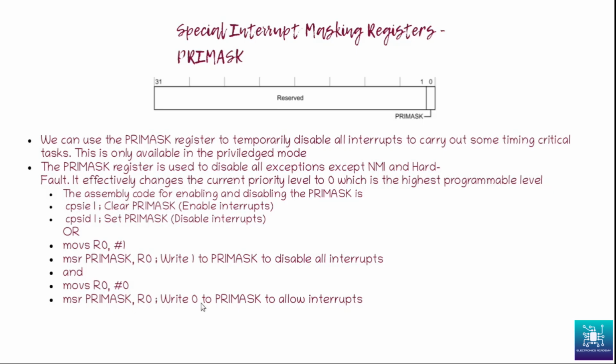We will see it more in our code, and as we discussed, these registers are not memory addressable, so they will have to be addressed through assembly code. So we'll have to have some inline assembly in our C code. We had discussed previously, and I said that you can absolutely do without assembly coding in the case of ARM Cortex M4 programming, but then again, it will be needed here and there for accessing certain control registers and so on.